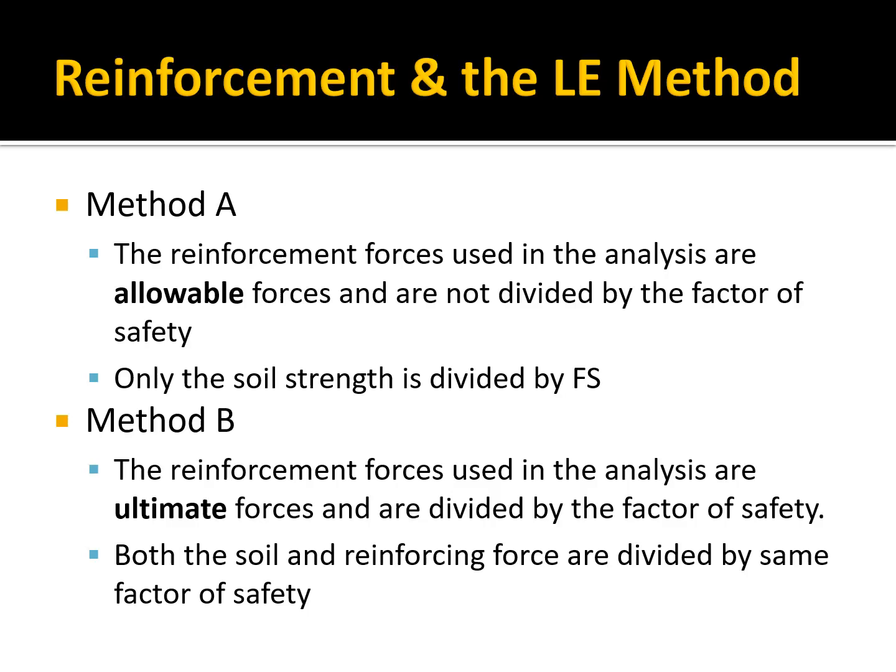In method B, the reinforcement forces used in the analysis are ultimate forces and are divided by the factor of safety. Both the soil and the reinforcing force are divided by the same factor of safety.